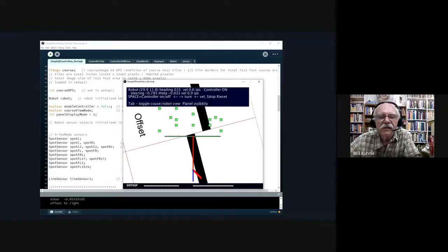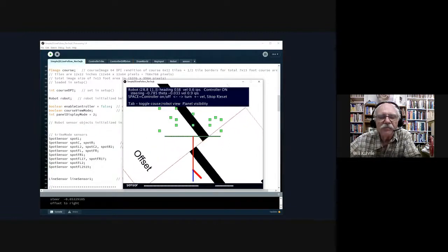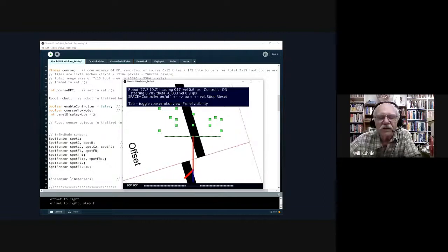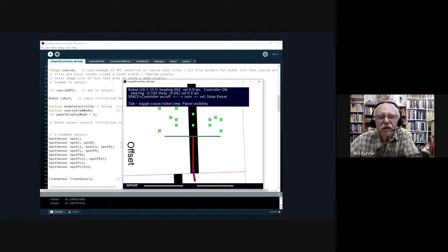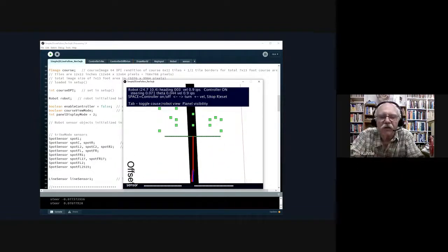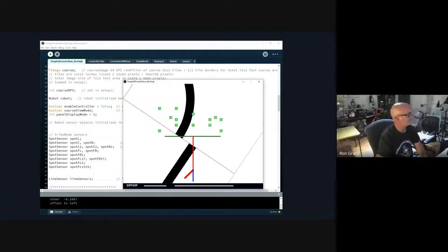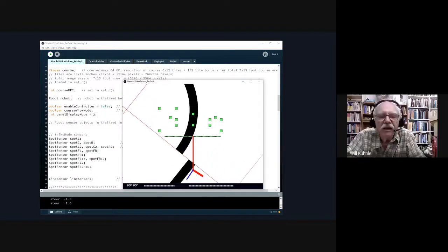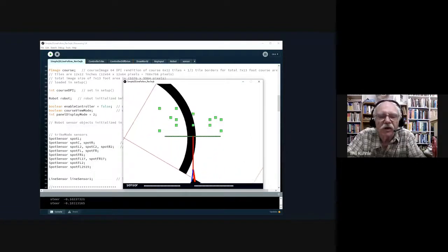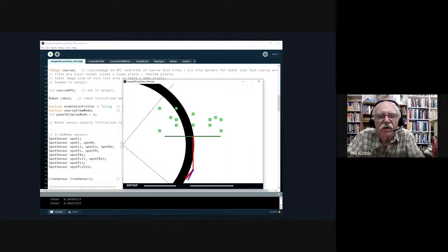Now, basically what I do is an open loop maneuver. My philosophy is that I'm following the line as long as there's a line, but when I come to a discontinuity or something changes, by the way, hit the P button. That's a closed loop response, and those closed loop responses are triggered by the fixed spot sensors.